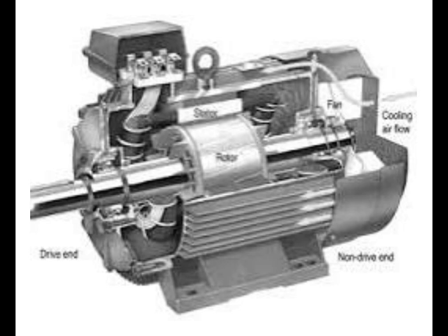The important parts of electrical machines include the rotor, stator, coil, magnetic core, shaft, bearings, and frame. The rotor is the rotating part of the machine. It spins inside the stator. When magnetic fields interact, the rotor begins to turn. This turning motion produces mechanical energy in motors or helps generate electricity in generators.